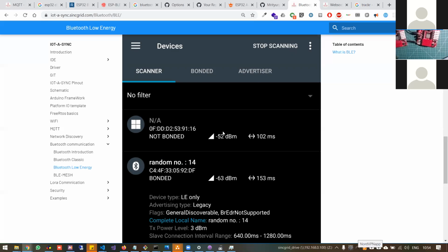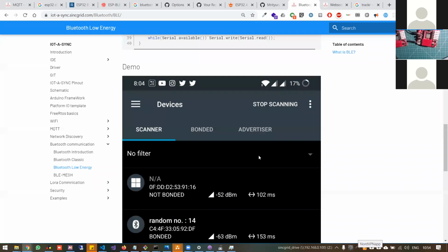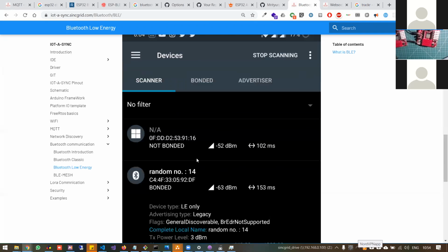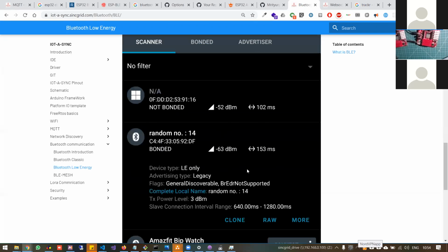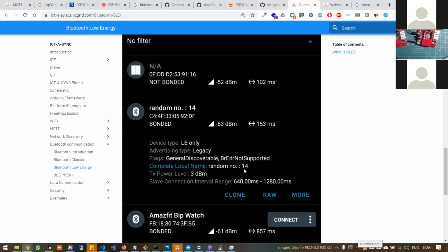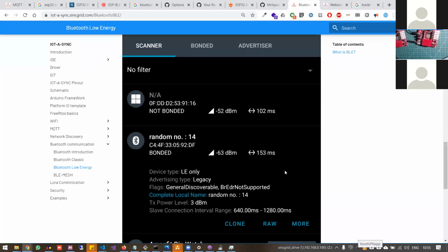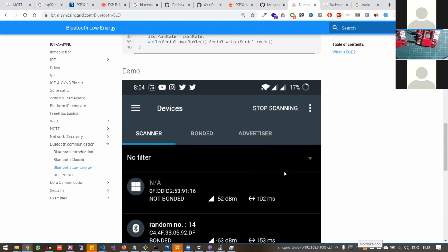You install nRF Connect, again an open source app available on the Play Store, and after connection, whenever we press the button, this number will change. It is broadcasting a unique value that can be received by any device. So this is another kind of M2M, machine to machine, communication, where some other tracker or module, not a mobile phone, is receiving it. This is another example of a piconet, in which one-to-one communication is being made.